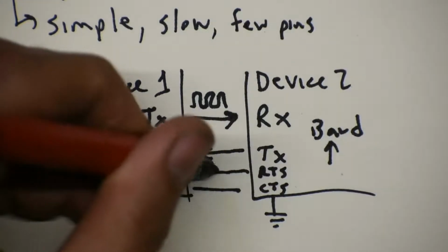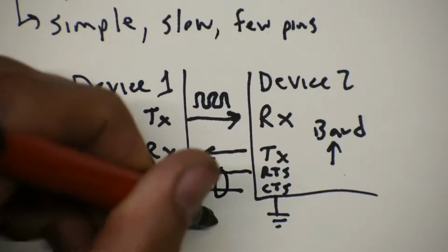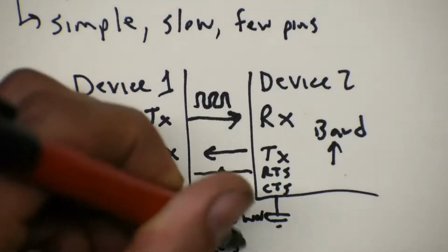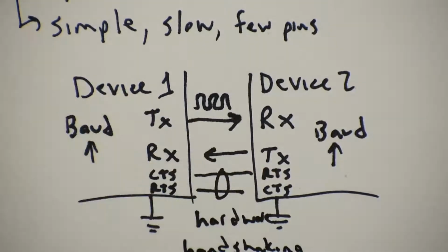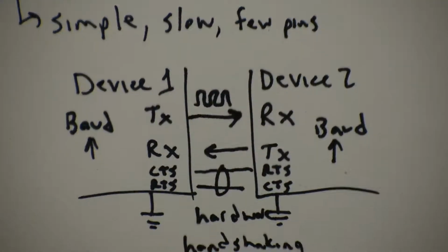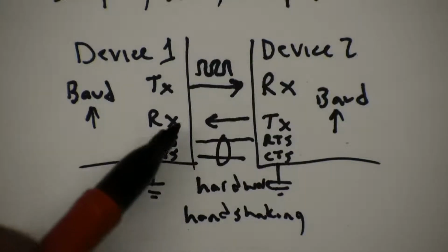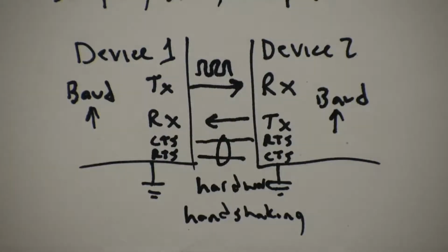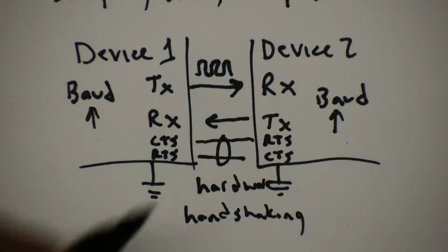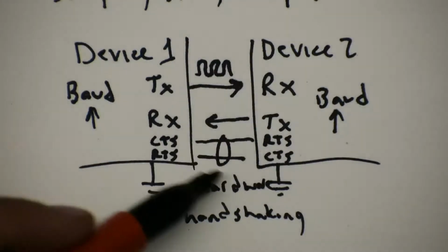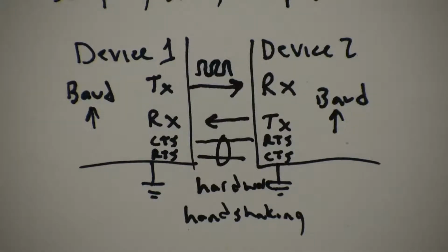and that's called, these two specifically, hardware handshaking, where the devices can indicate to each other, hey, I'm not ready, so please don't send any more data. And in that way, we can kind of guarantee that we never lose any data. We'll probably leave that off in this example. But if you want to use 2 more wires, you can connect those and get kind of guaranteed transmission.